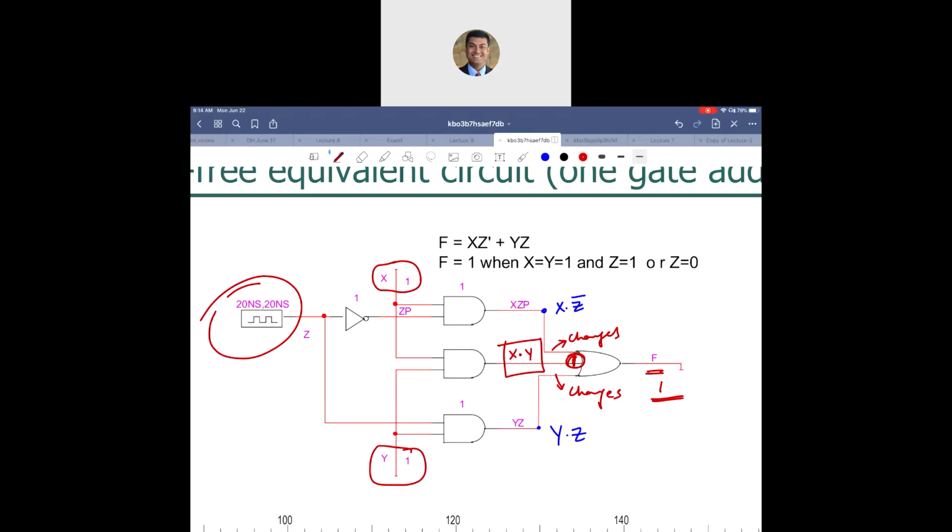All right, so let me see this way. Couple of questions. So basically, adding redundant groups of ones can eliminate the glitch. You are right, Michael. By adding the redundant prime implicants, that's how we fix the glitch. But each fix will be related to each condition that we are trying to fix. And when we go to a 4 variable example, I will talk more about that. There's another question. Do you have to add in every RPI case to eliminate glitches? Yes, you do.